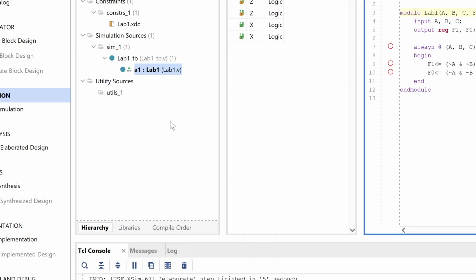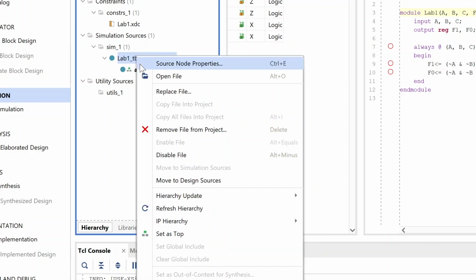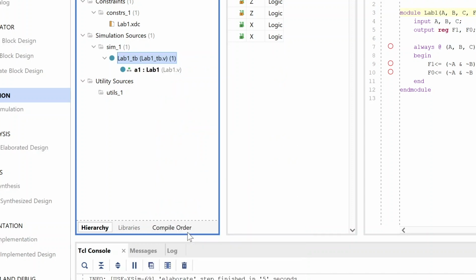Before running a simulation in Vivado, it is useful to understand how file hierarchy works. By right-clicking a file and clicking Set as Top, the file will be treated as the main file to be executed for the project. For example, if your project contains multiple test benches for multiple modules, by setting a master test bench file as a top file, it allows you to simultaneously test multiple test benches.